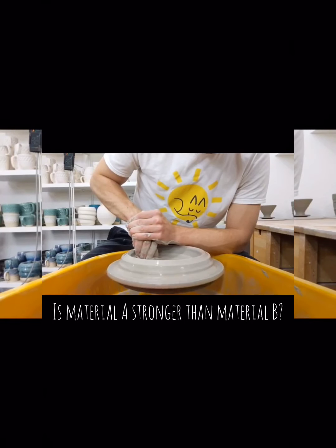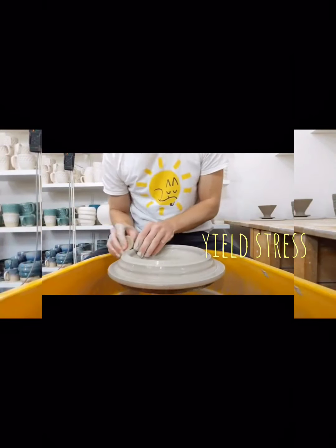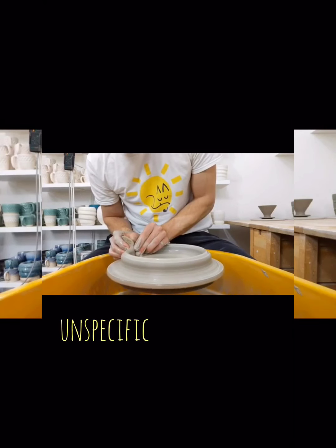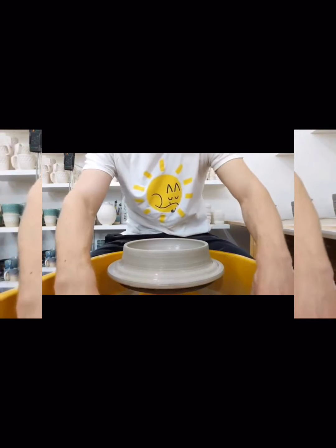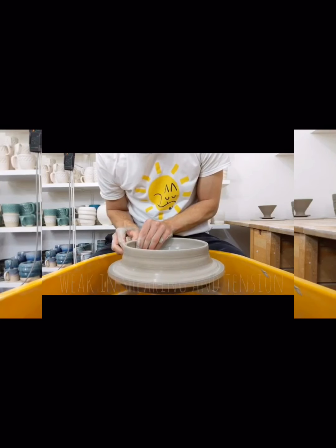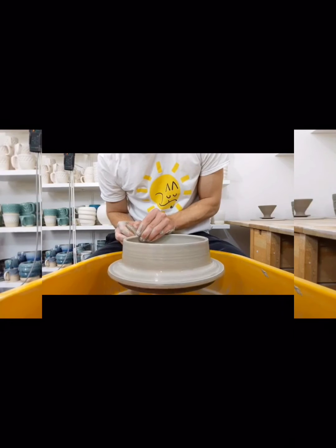Is material A stronger than material B? Unlike yield stress of a ductile material, strength of brittle material is unspecific until a particular type of test piece is fractured in a given manner. Materials like ceramics are weak in shearing and tension, but have strong compression with high softening temperature. Ceramics are hard and brittle.